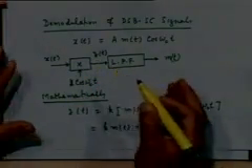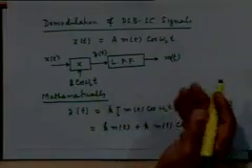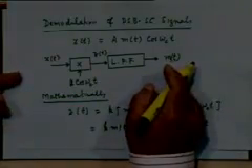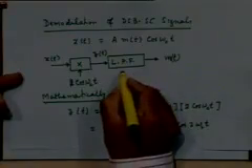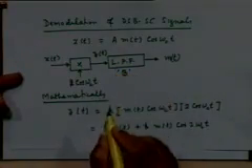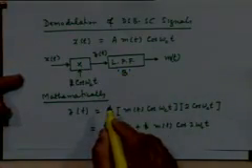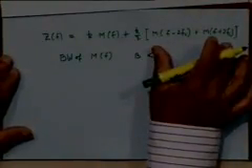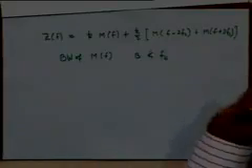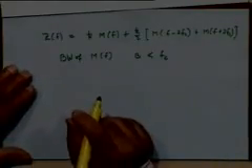The desired signal has a bandwidth of B, and you only want the desired signal to appear in the output. So this low pass filter should have a bandwidth of B, and naturally the components centered around 2fc would be eliminated.